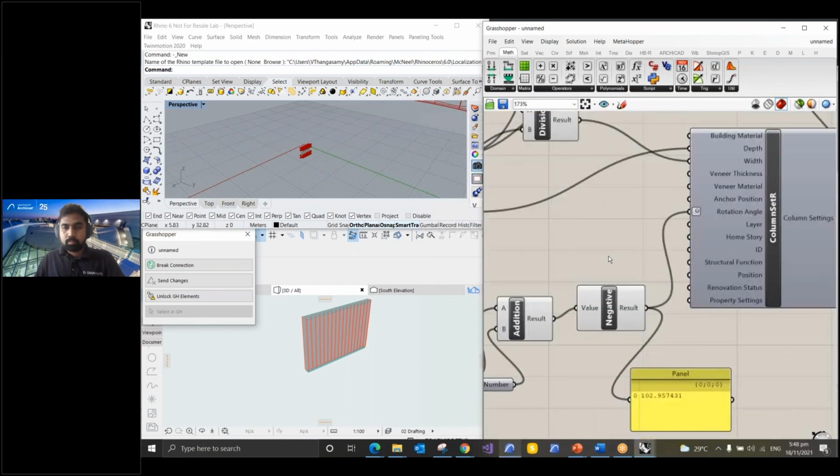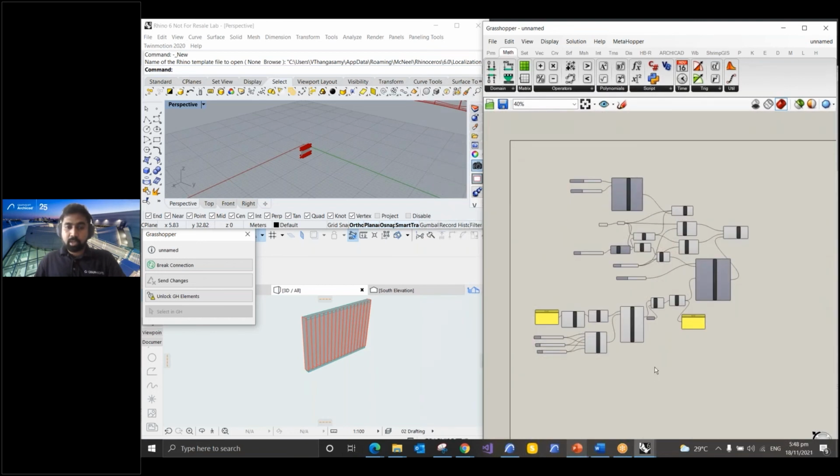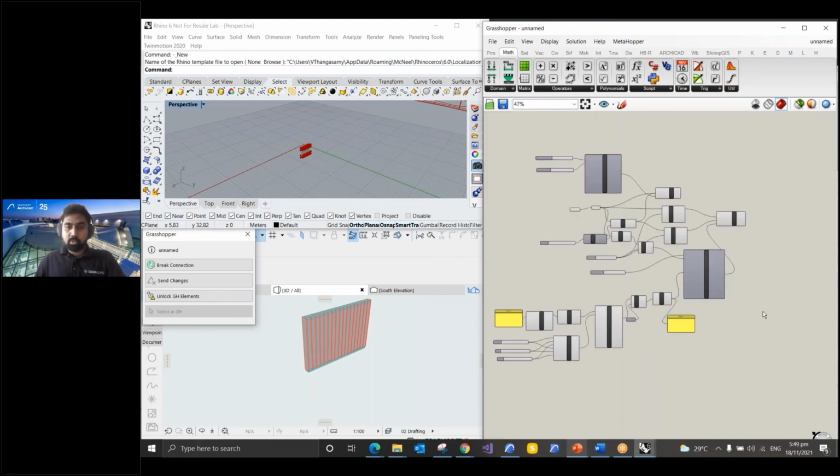So next week, we will try to do some twisted towers and also some roofs, triangulated roofs, and then try to schedule it inside Archicad. If you are able to create a twisted tower by yourself, I will send you the steps to create it by just drawing a polyline inside Archicad, and then using that polyline to create the twisted tower. I will send you the assignments. Probably you'll be able to try it yourself, but if you're not able to complete it, maybe I can show you in the next session.